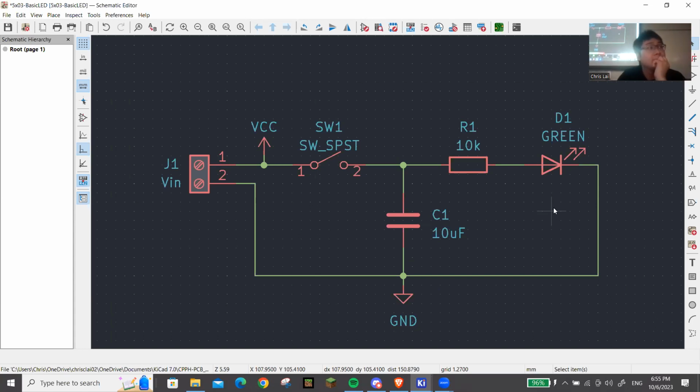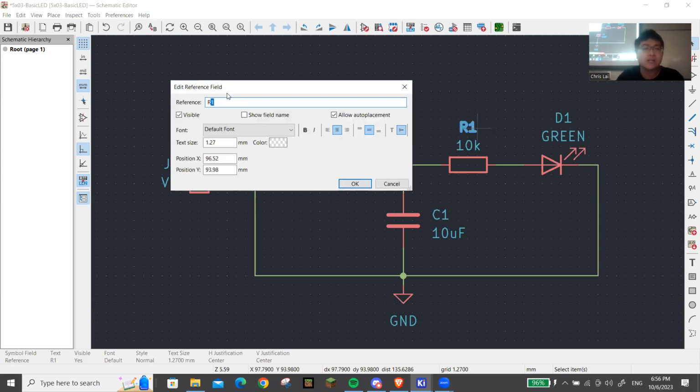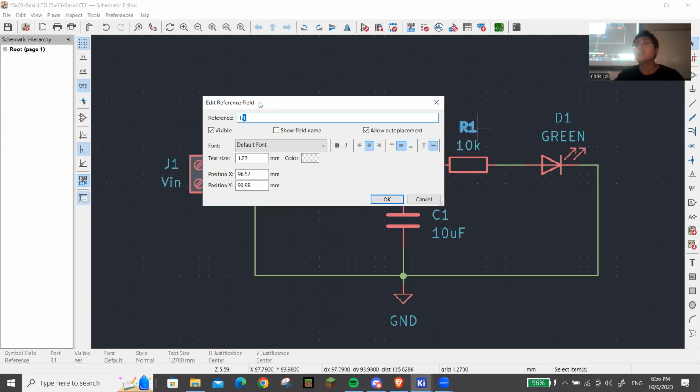Yeah. I think there actually is a way to do that. There is? At least in my version, there's annotate schematic. It will do the entire thing. Right, but annotate schematic is for R1, R2, C1, those labels. So this one is actually called a reference field. When you generate a bill of materials for your PCB, that's what's going to say that's resistor 1 or that's resistor 2. I see. Resistor 1 and resistor 2 can be the same thing, like 10K, which is the value field, but they can't be the same reference field.